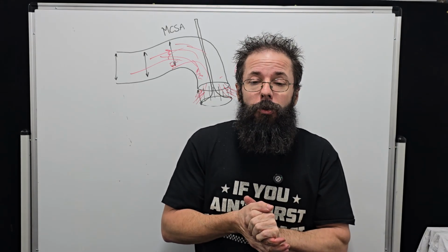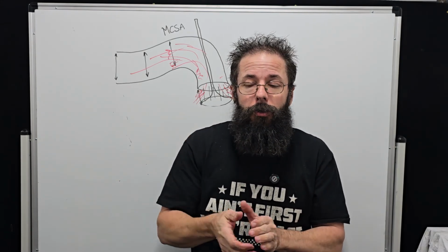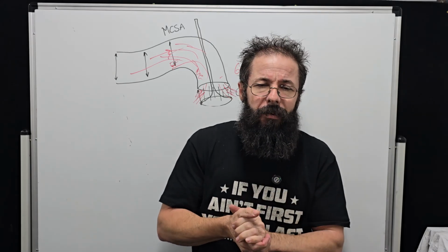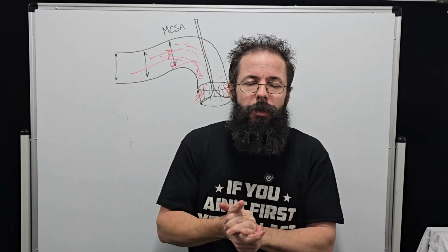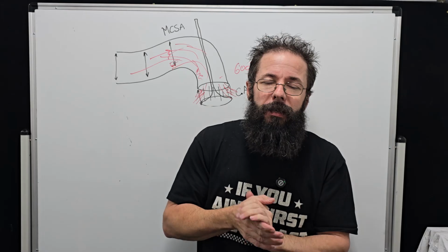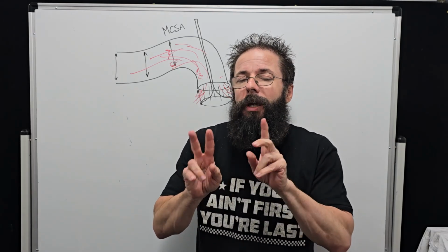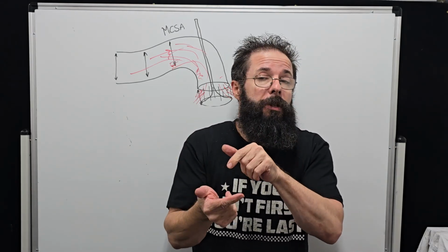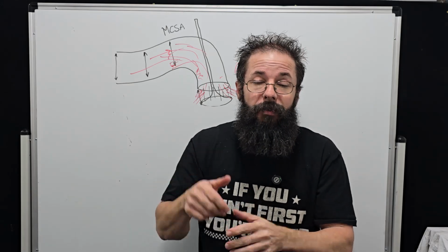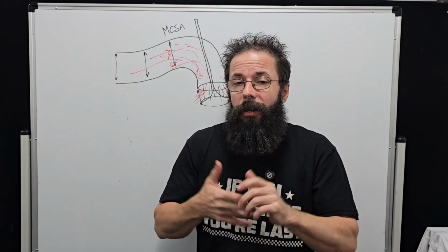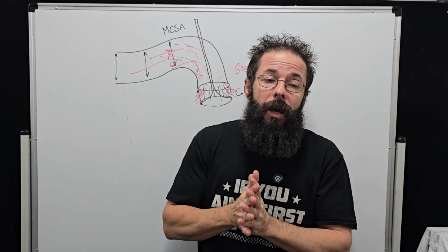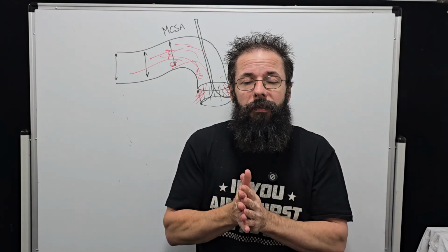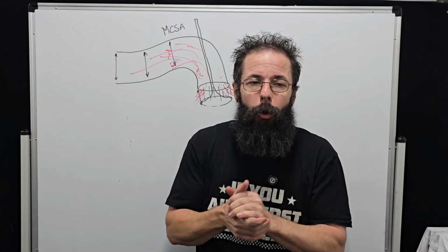And this is applying to Bradford's engine that he's talking about. It had 2 inlets, 1 exhaust, the 3 valves in the Fords, the Mustangs, and so on. We did a little bit with these probably a decade ago. They also had bias ports, so they actually contributed to swirl. They had the flat valve, similar to the CA, for the guys that know the Nissan stuff, similar to some of the early Ford stuff with the flat valve in the port, dual port.